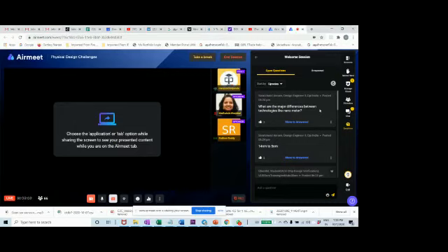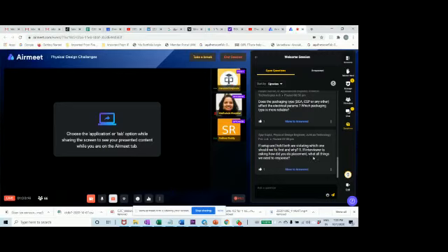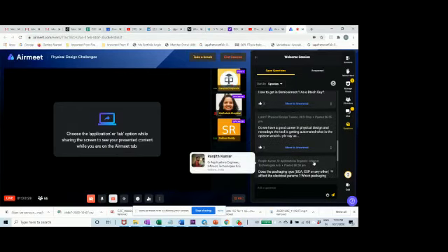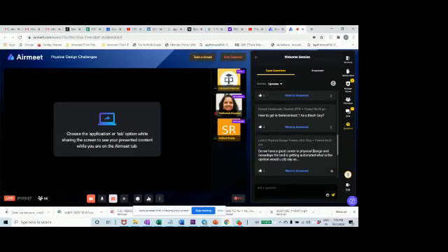What are the major differences between technologies like 14 nanometer to 5 nanometer? Oh yeah, once you start packing a lot of things into smaller regions, there are different aspects of signal integrity and power integrity. The closer you bring things, the tougher they become in terms of parasitic effects, parasitic capacitances, and their effects on the transistors. And the other problem is the transistor is so small that a very small current can turn on the gate, right? So your transistors are very sensitive to any fluctuations, both in terms of power supplies or inputs and outputs. And then you have so much parasitics in the metal wires coming into the picture, which will aggravate the problem of transistor functionality.